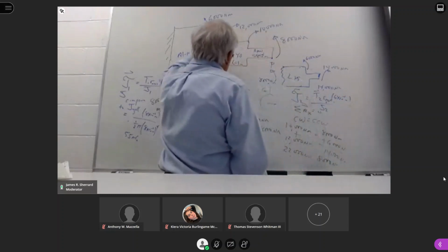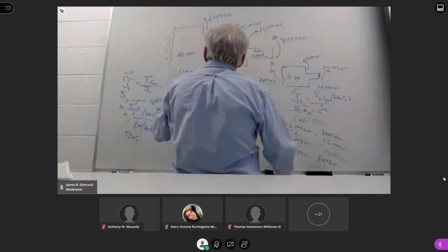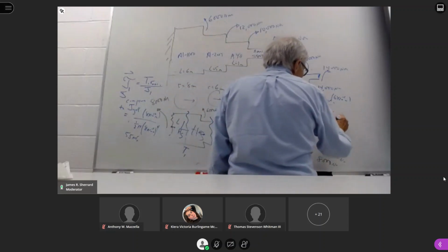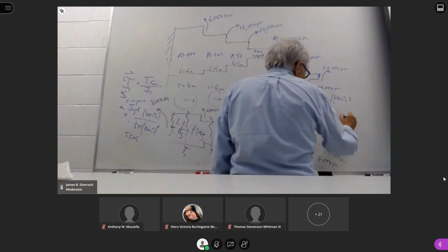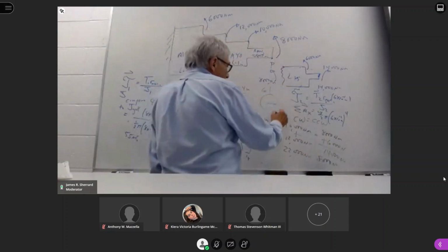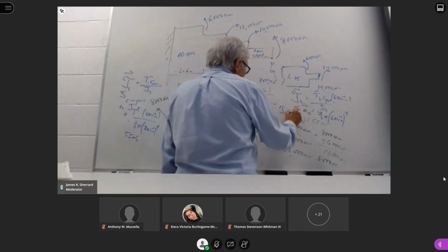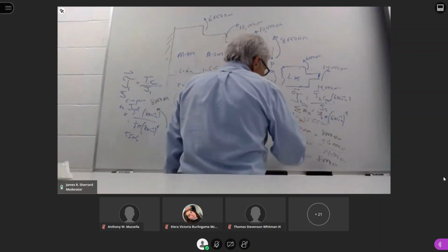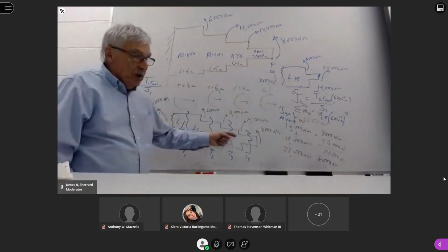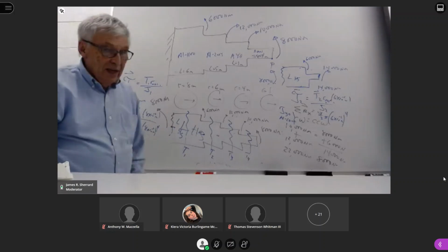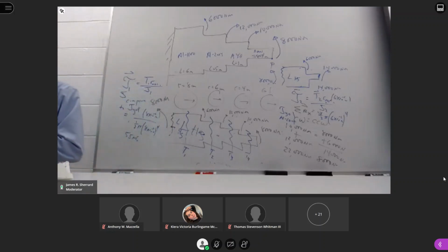And my J, since this is solid, is 1/2 pi times 6 times 10 to the minus 2 raised to the 4th power. Whatever this value is, we compare it to the yield value for aluminum 2014, and we do that accordingly going across. Okay. Any questions on how you could find the safety on that?